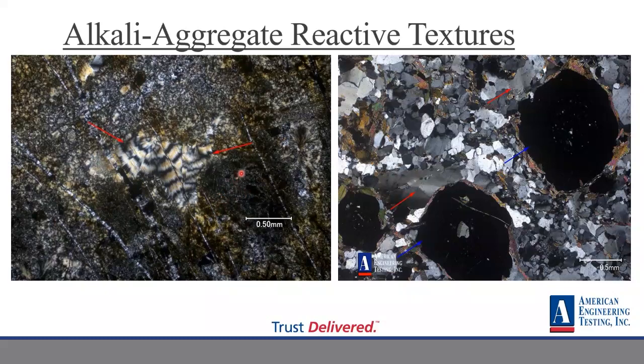But that's one of the minerals that we definitely look for, and when you're doing the particle count of the C295, the hand sample stuff, if you have, say, 5% chert, you probably should get your aggregate checked to see if it has alkali-silica reactive expansive properties.